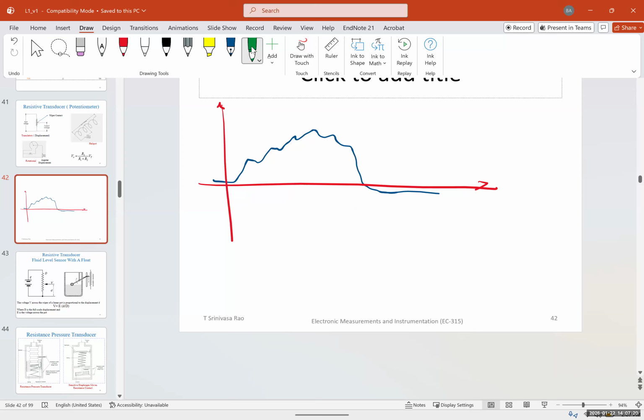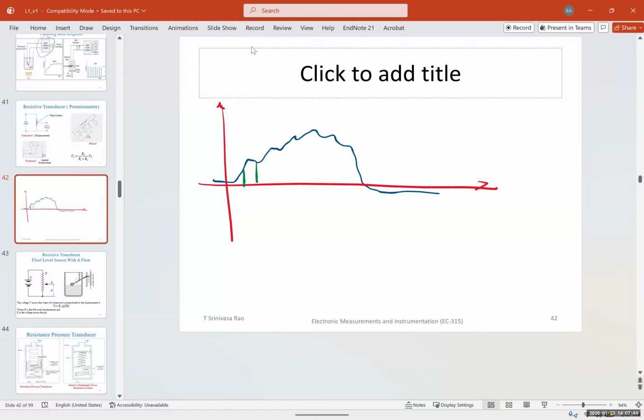So imagine I give you the signal, and I ask, make it a digital. How can you do that? Imagine the signal is coming from a function generator. It's an analog signal, and I ask you to convert this to digital. So we do this through a process called sampling, meaning with a fixed interval, let's say every 0.1 second, I take a sample from that signal, and I record that, and I save it somewhere.